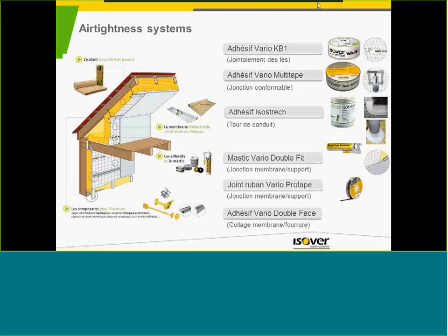And all the components of the systems are tested by different standards and European standards, and each component is tested both in shearing and peeling resistance. For example, for the mastic, the shearing resistance and the peeling resistance are realized on different types of support. So we do it on concrete, on metal, and on wood, and different types of metals, in fact.